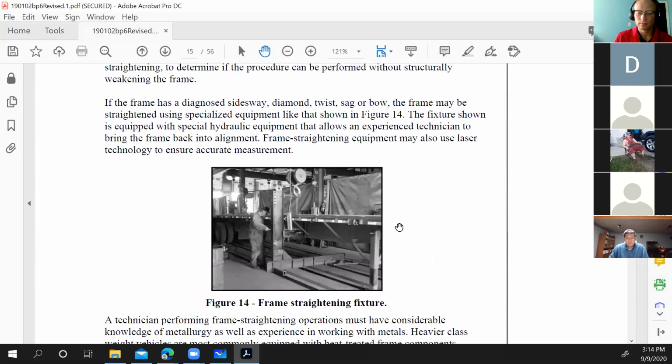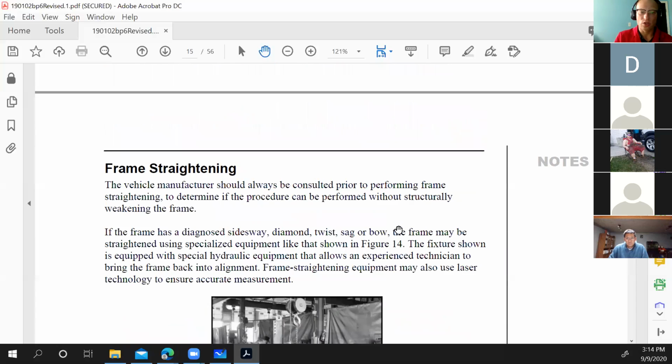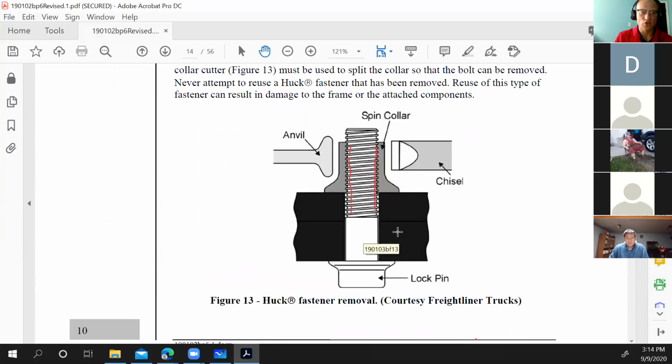What about a plasma cutter? A plasma cutter would do the same thing. You have less chance of overheating, but you put quite a bit of energy in there quite quickly. Yeah, it still gets pretty hot. The problem with a plasma cutter is that when I put it in here, it goes in however deep it's set up for, no matter what, right? It's going to cut into here and it might nick part of the frame as well, okay? So a plasma cutter is probably even worse than a torch.